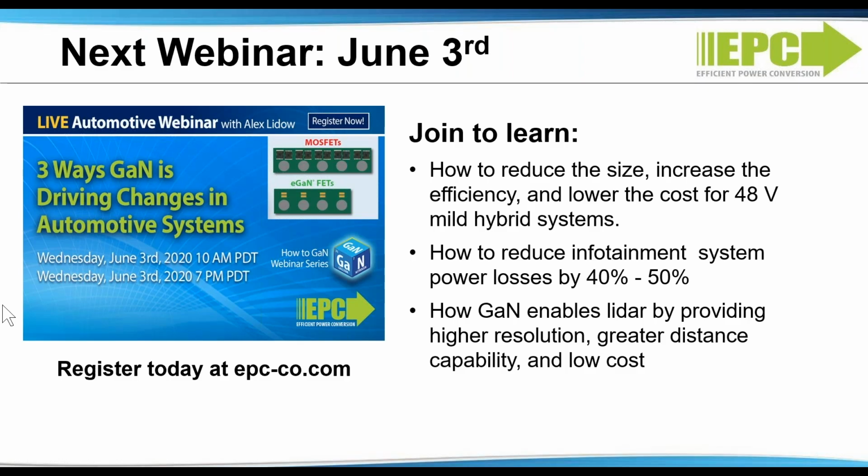In the end, we did a comparison. It's in our book, where the difference between a MOSFET and a GaN in a 1 megahertz resonant converter was about 30% lower power losses. And that was compared against an older generation of FETs. I'm sure it's better than that now. But everywhere we go, when you have a 48 volt input, you're always going to get about 30% better efficiency using GaN. Resonant, non-resonant, hard switch, 1 megahertz, 500 kilohertz, doesn't matter. It always comes out so much better.